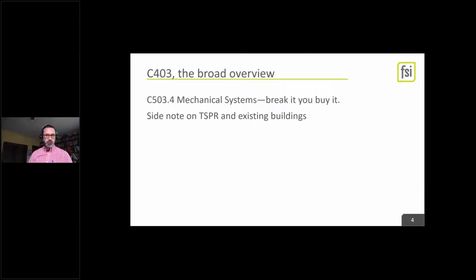Otherwise, from chapter 5, you get the equipment economizer exceptions that Duane said. There's some capacity limits on that. Again, you really have to treat even tenant improvements as becoming a little bit more of a whole building issue as we start having required DOAS, required TSPR.